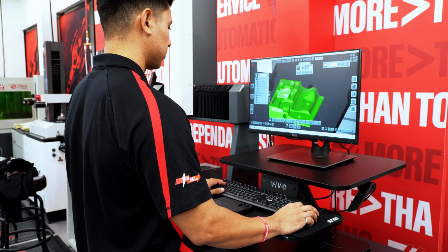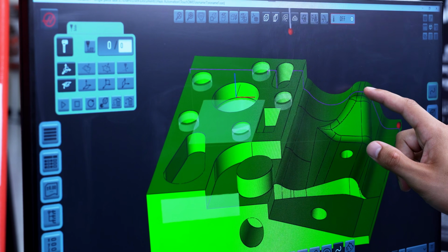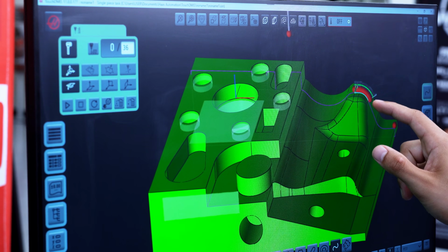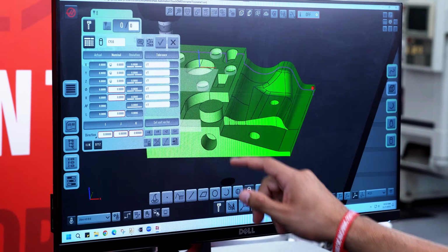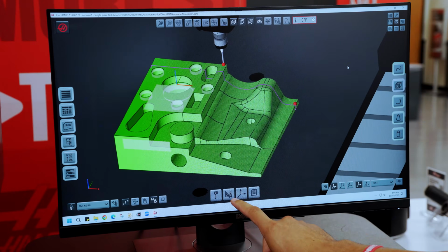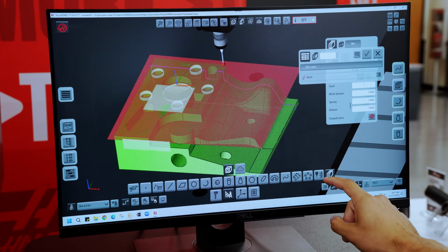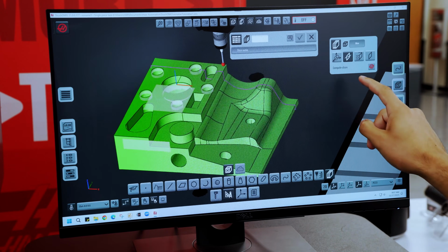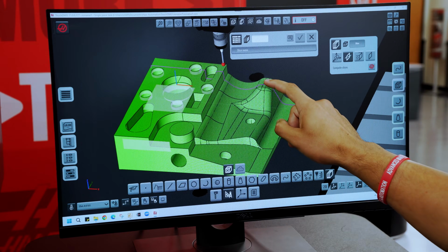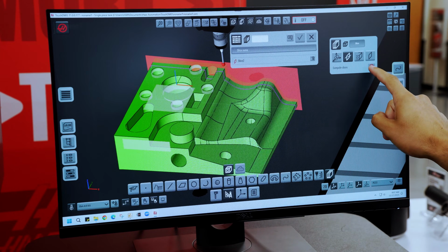So far, we've looked at setting up our measurements using the mouse, but it's called TouchDMIS for a good reason. If you're connected to a touchscreen monitor, then you can perform many functions without the mouse. To see how that works, I'll tap on the Construct icon, then the Slicing icon, which opens the Slicing window and Results window. I'll select the normal Endpoint icon, tap on the surface I wish to create my slice on, then I'll click Compute Slices and confirm with a check mark.